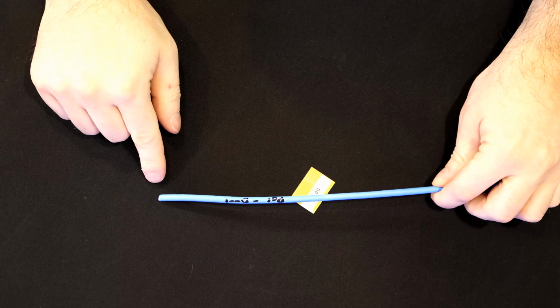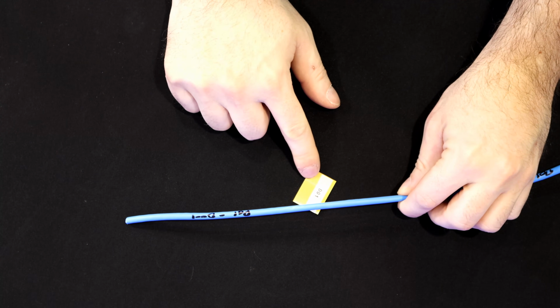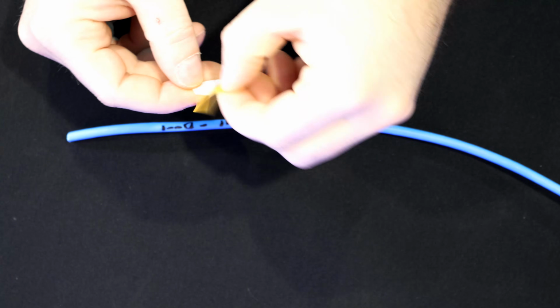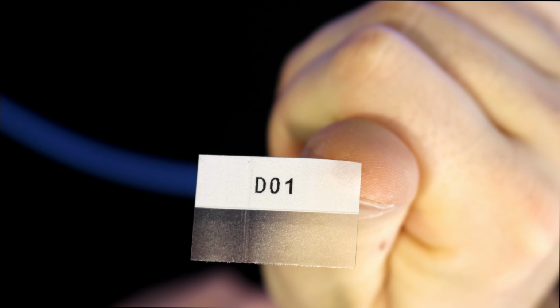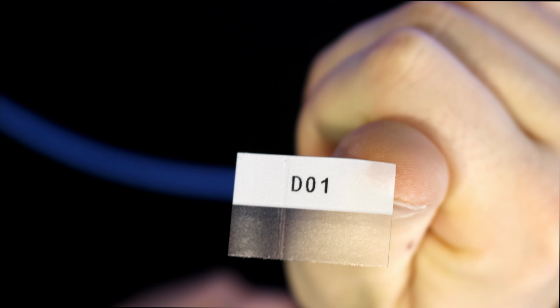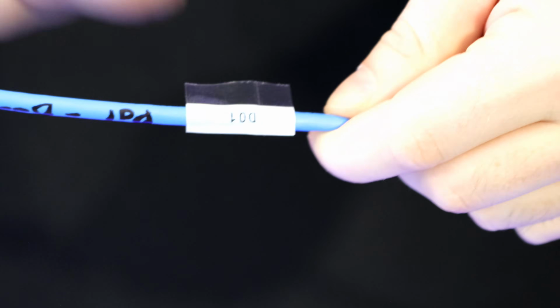So I have that same piece of wire that we labeled D01 with the Sharpie, and now we need to unwrap the wire wrap. All we need to do is just pull the label tape off of the back. And you can see on the bottom that it's clear and on the top it's white with our black label. So we need to put the white around the cable. So we'll stick the white piece on. Make sure that it's pressed down. And then we'll just wrap the white clear around it.